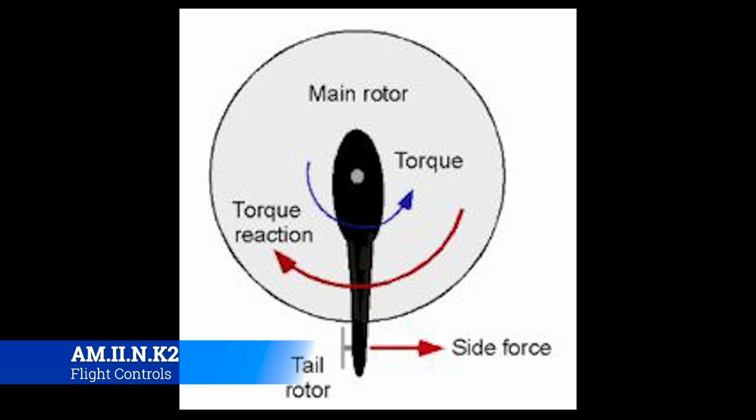Now, the same thing happens if you deload the rotor disc and you drop the collective and the helicopter wants to sink. You don't want the engine RPM to spike, because all of a sudden there's no load on it. It can just keep on going. It'd be like if you had a diesel that's trying to pull something way uphill, and all of a sudden you detach the trailer, it's going to take the same amount of power, but a fraction of the weight, and just launch itself over that hill. You don't want that. So whenever you drop the collective, you have to roll the throttle back down to keep that from happening. Now this all gets overcome by using FADEC, or full digital engine control, to keep that from happening.